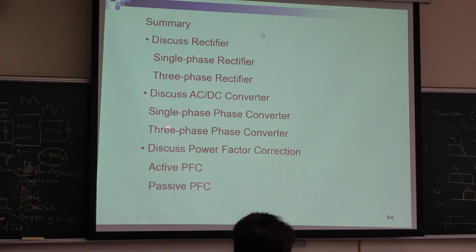So we discussed single-phase controlled converters. We also discussed a three-phase converter. So we avoid using control. We avoid using feedback. So what can we use? We try to use discontinuous mode. However, if we use discontinuous mode, the current ripple becomes very serious.